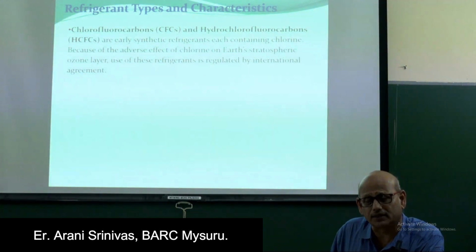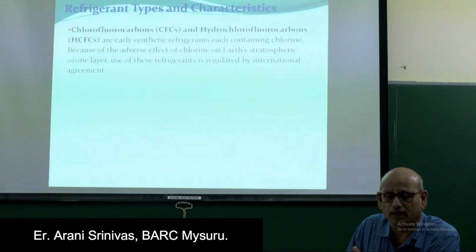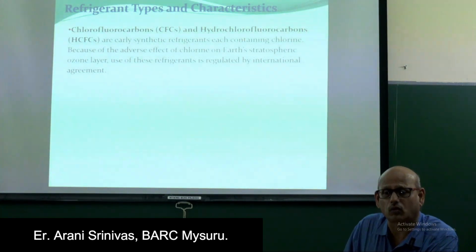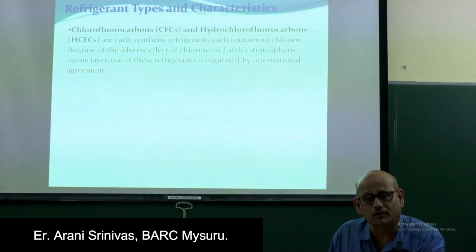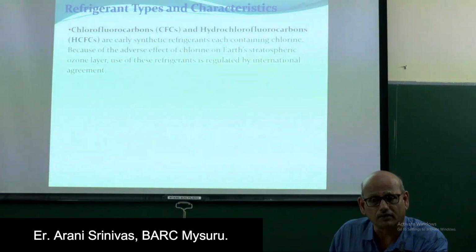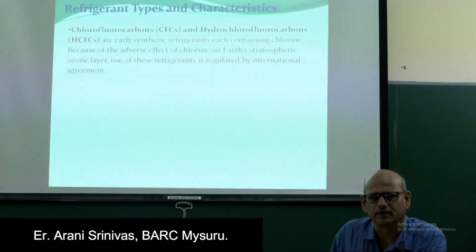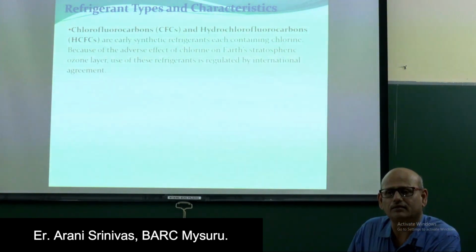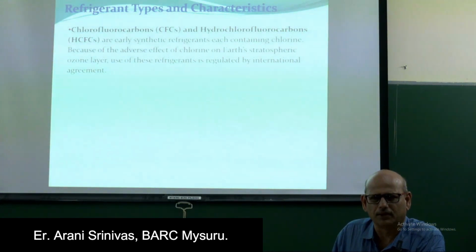They used to bring down the pressure to less than 10 mm of water, so that water starts boiling, and that boiling water cools the other water, the chilled water, and that water was circulated. Now maintaining that much low pressure was a problem. So then vapor compression systems came.